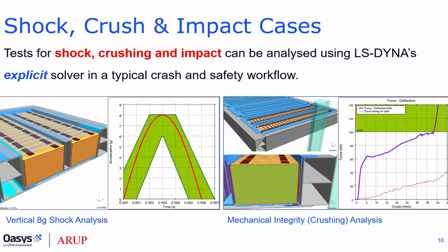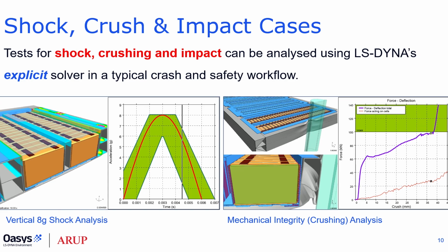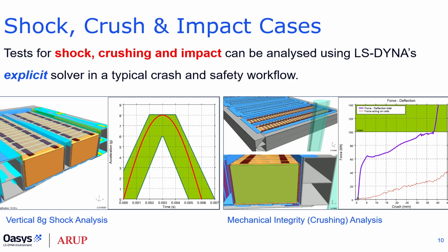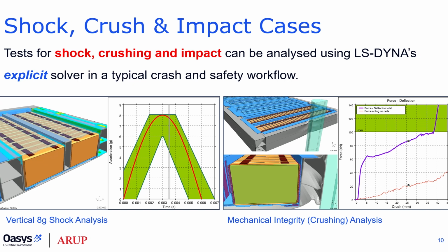So I'm just going to touch on the cases that can be analyzed using the explicit solver in LS-DYNA. In this case, a shock analysis on the left and crushing on the right of the slide. These cases are very similar to typical crash safety load cases, and in the case of crushing, quite non-linear in nature. Therefore, the explicit solver is a good choice.